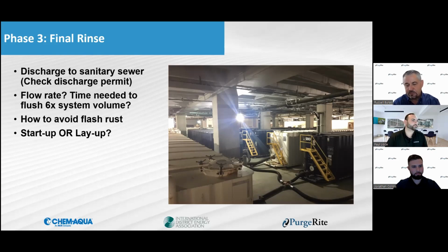You sometimes have to get into creative solutions. This one involved 14 frac tanks that we created. 10 of them were a water battery, 21,000 gallons apiece, connected together, and we were able to meet the requirements to rinse it within certain time frames, get enough water through it, and have a place to store it, because believe it or not, the pressure is very low in that area.